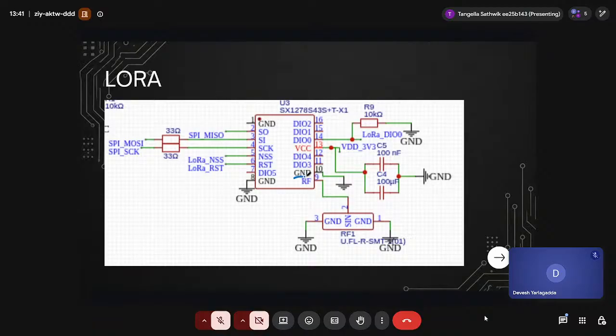We can see first the ground pin is connected to the common ground, and the VCC is connected to the VDD 3.3 voltage, and also the decoupling capacitors are placed here. And we'll see the next connections also. Here you can see two important pins, SO and SI.